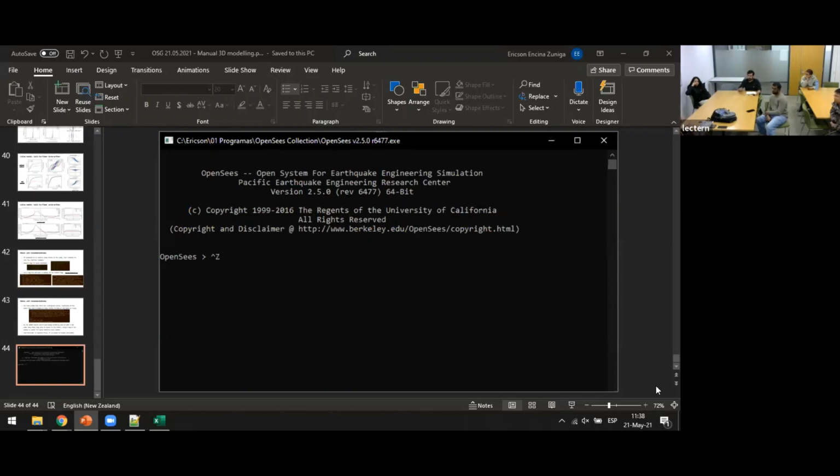No, what I did was I separated the section. So you have the double T and the topping. I took the web and modeled it as a frame, as a line element, with the pre-stressing, because it's really long and I don't want it to start generating a lot of stresses. And then the top flange and the topping I consider as just one section. And that was my layer shell.